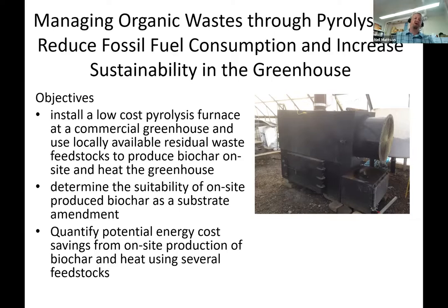We worked with a partner called ClearStack, a furnace company out of Connecticut that makes a low-cost pyrolysis furnace. This was their first installation of that pyrolysis furnace into a commercial greenhouse. You probably talked a little bit about the biochar manufacturing process. Pyrolysis is heating in the absence of oxygen or in low oxygen conditions, and you drive the combustible gases from the feedstock, and those get combusted to generate heat in this case, and then a lot of the wood residue is still left behind as charcoal or biochar.